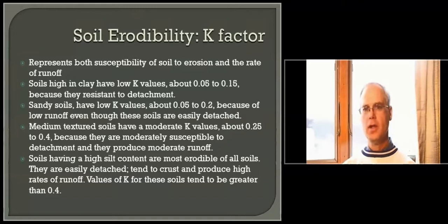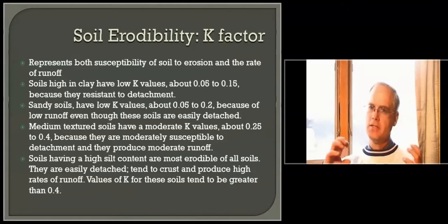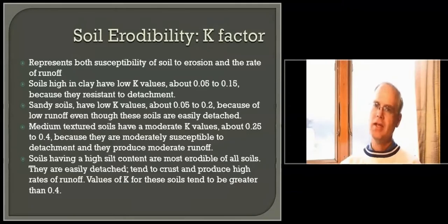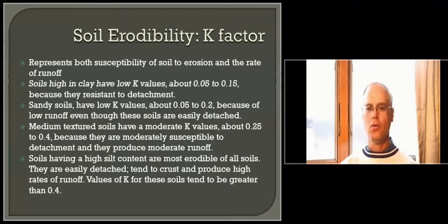There are a couple factors related to erosion. One is the K factor, and I realize a lot of writing here. But what the K factor does, it represents both the susceptibility of that soil to erosion and how fast it will run off. Soils that are high in clay tend to have a low K value. Why? You said, well, they run off fairly easy. Yeah, but clay actually is very resistant to being detached. It kind of glues to itself. And since it glues to itself, it's going to hold itself in place. If it gets detached and broke loose, yeah, it's going to wash real easy. But it's tough to detach it, so it's not easily eroded.